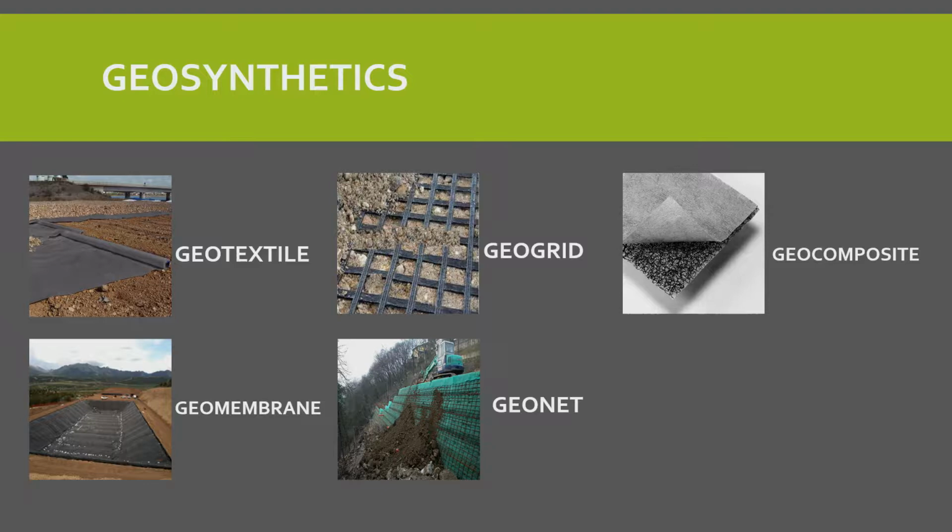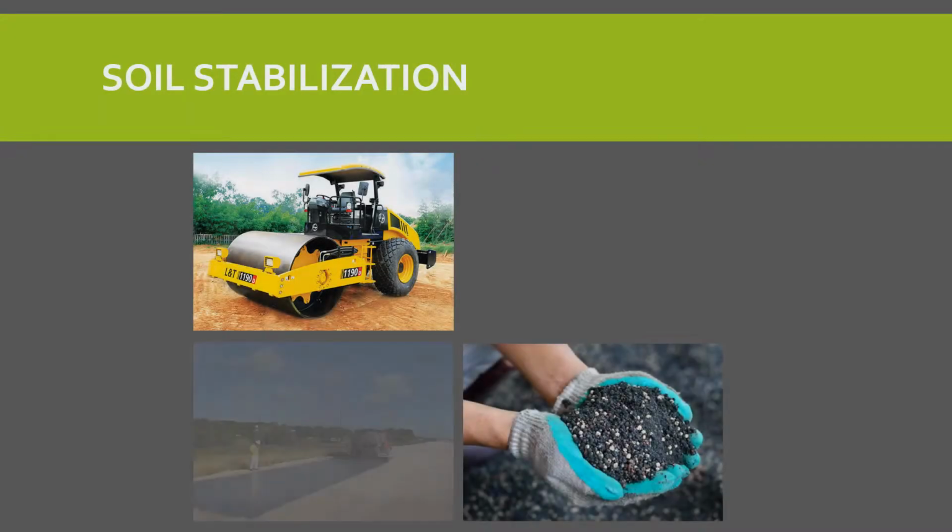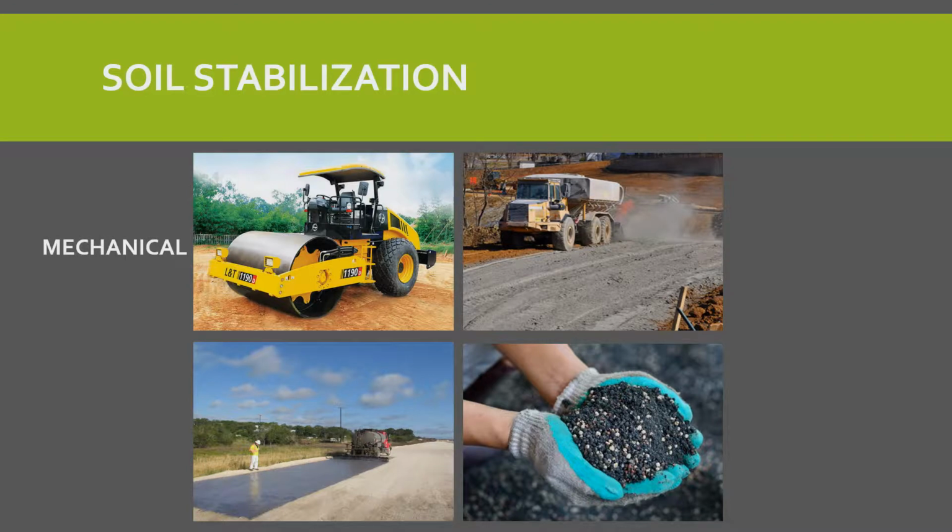There are four methods of stabilizing subgrades: mechanical stabilization, cementitious stabilization, asphalt stabilization, and the non-traditional additive stabilization. Each stabilization method intends to improve subgrade strength and plasticity, aggregate interlock, reduce pore connectivity and air void content, and consequently susceptibility to moisture ingress.